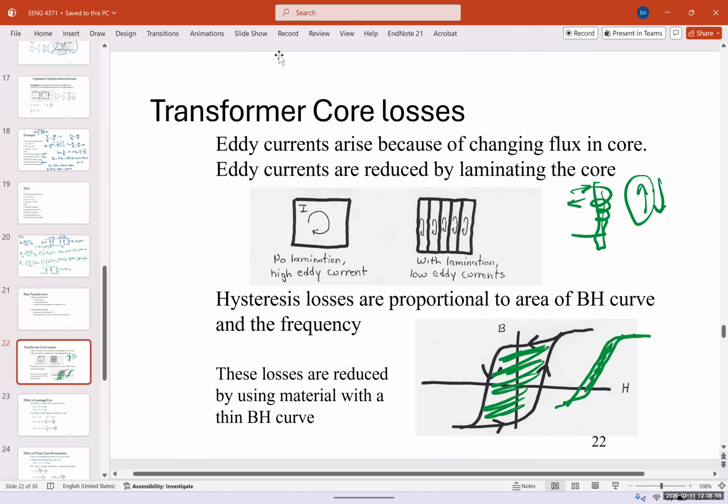Laminations, these cores, do they need to be insulated? No, they don't need to be insulated. That's a great question, by the way. Most of the time you don't need to, so if I rip them apart you would see it's just sheets, and sometimes to keep them together, they put glue between them. I've seen that, or a type of oil, but no, it's not necessary. Depends on your application, but not necessary.